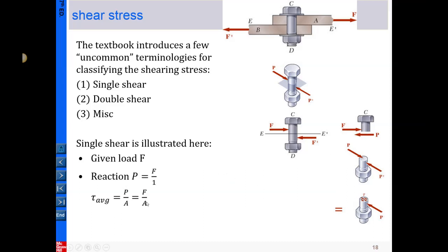And again, for this case, that stress is shear. So here we still take the same formula, but you need to identify this stress is shear stress. So here we're using tau as the symbol. And again, here we divide the force by the cross-sectional area. That is in the average sense. So in the textbook in 331, this class, we're using average. In reality, the distribution of the stress is not uniform throughout the cross section, but it's okay. At the beginning of mechanics of materials, we simply take the average.